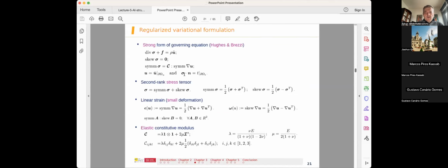So let me go into how we do that. First of all, we go back to the formulation of our membrane problem, where we have this force equilibrium equation, divergence sigma plus F. This time we are talking about dynamics, so it's equal to rho times acceleration. So as opposed to the static problem of equilibrium, we have this dynamic equation of motion, where U and sigma and all that are functions both of x and t.